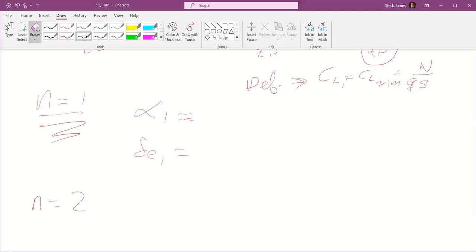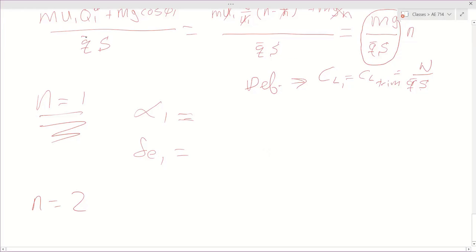No guarantees here. So I got for no load factor, alpha of minus 0.004 radians, or minus 0.21 degrees. So check me out because I don't know if this is right. There's a lot of numbers. And then for elevator, I get 0.1073 radians, or 6.15 degrees.